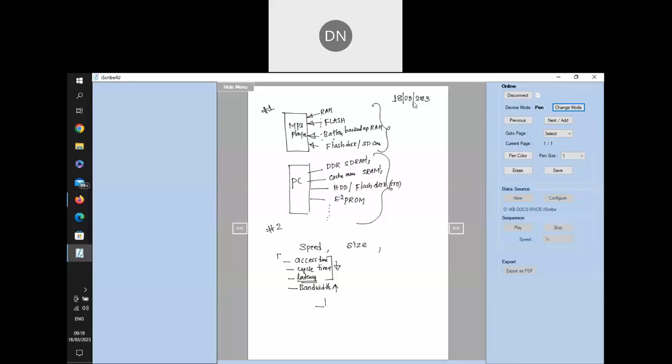If the same cell is manufactured using 5 transistors, the space is 5 times more. That is why, as we study further, SRAMs will take more space and DRAMs will take less space. So size is a crucial factor. When you're providing a large amount of memory in today's laptops, there is no affordability to increase the size of your laptop just because of the memory. So size is also crucial.